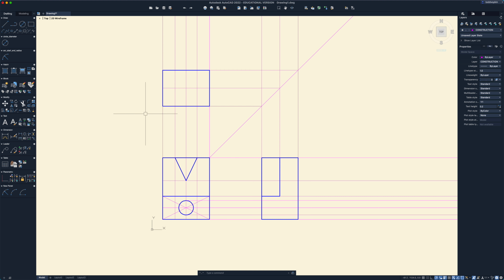Okay, and I know that that happens to be a line going across if we look at our top view. So I'm going to make sure that I'm in the object layer, L enter, I'm going to draw that. This is the top of that ledge down here. This is the other top of the ledge down here. And the bottom of the V will be this line that's in the middle.